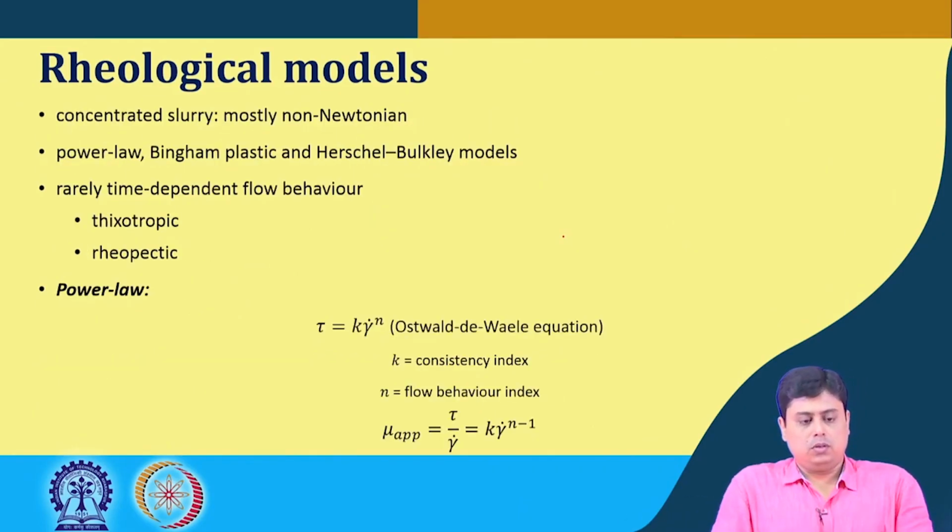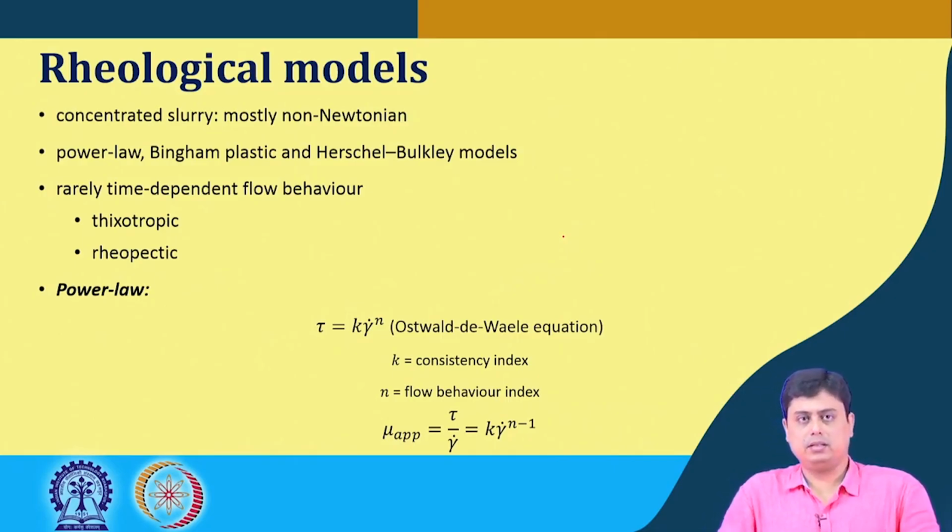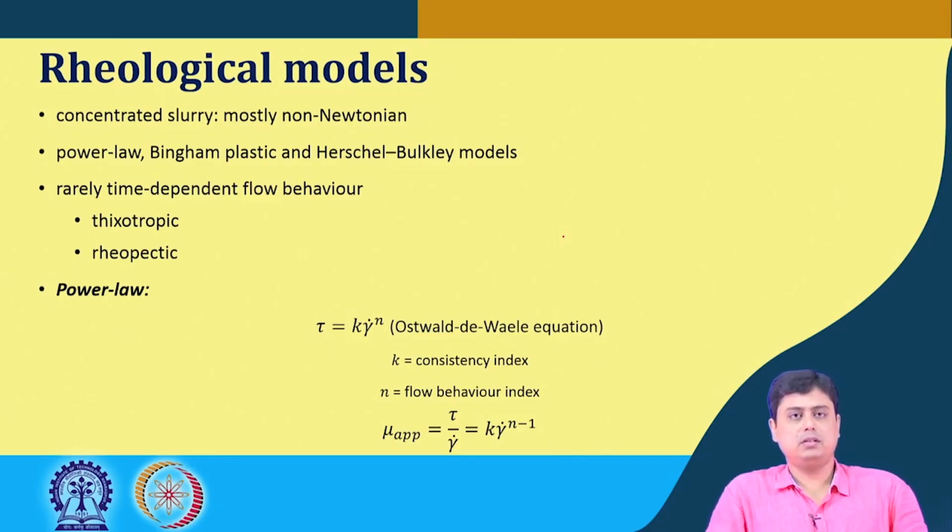Now for concentrated slurry, which mostly behaves as a non-Newtonian liquid, there are several rheological models available, like the power law, Bingham plastic and Herschel-Bulkley models. There are also slurries, though rarely in practice, which exhibit time-dependent flow behavior, like thixotropic or rheopectic materials.